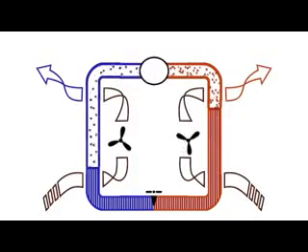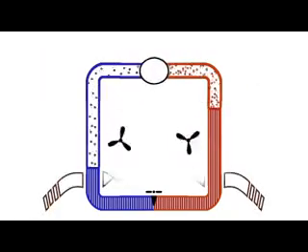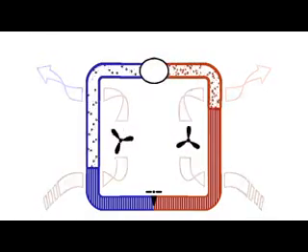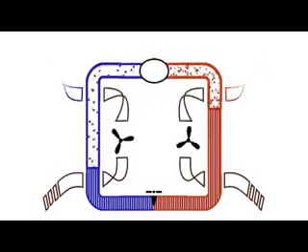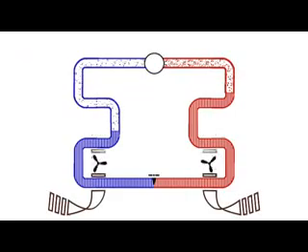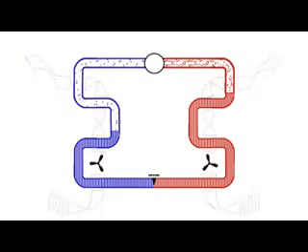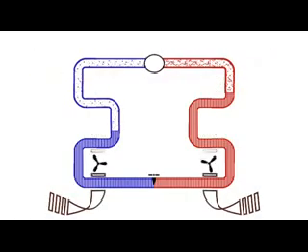Now, since the air blows across the pipe for the purpose of moving heat, efficiency dictates that we would prefer to maximize the surface area of each pipe to facilitate heat exchange. We will draw it like this, as a squiggle, and refer to each heat exchange squiggle as a coil, though it may, in practice, look more like a series of metal fins.